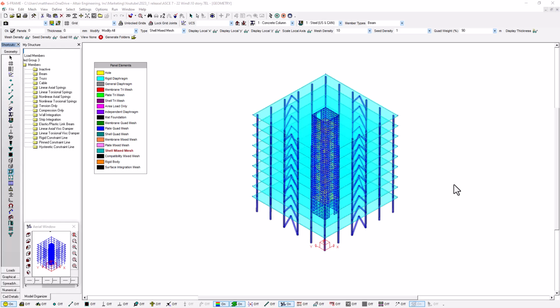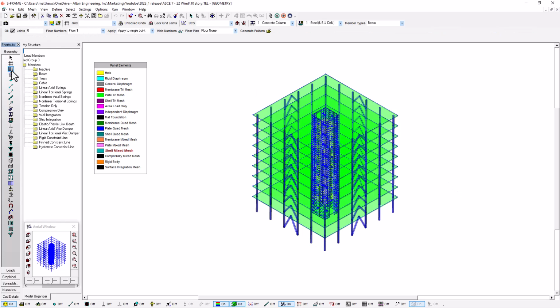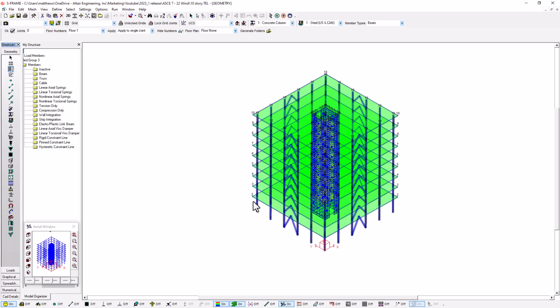The first one being a 10-story structure that is relatively square in its plan. We've got a core wall at its heart and also some external bracing, as you can see. All my floors are modeled with rigid diaphragms, and you'll notice here if I just go to the floor definitions tool that I have floor definitions starting at 1 and working their way up sequentially from 1 to 10 with no gaps as I go up.